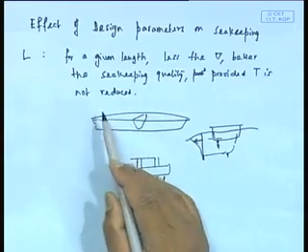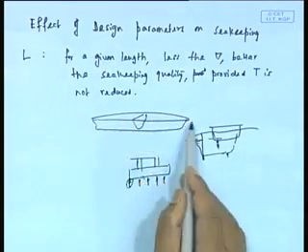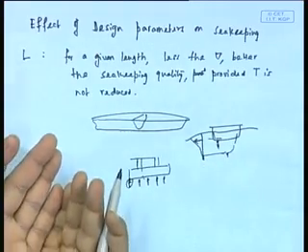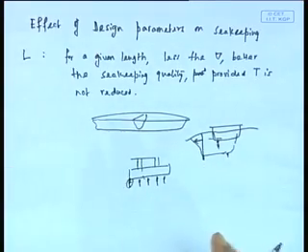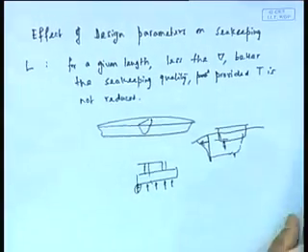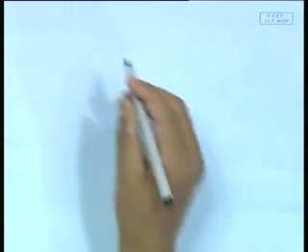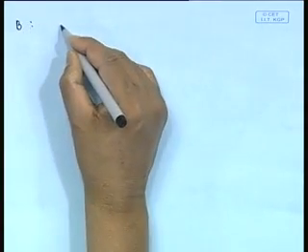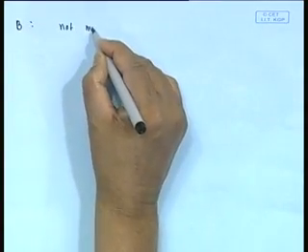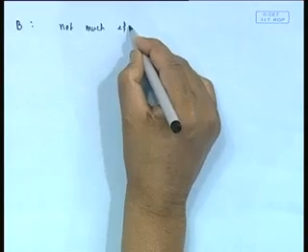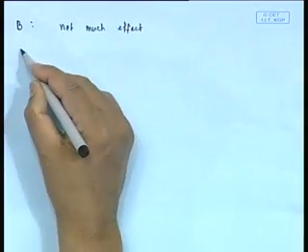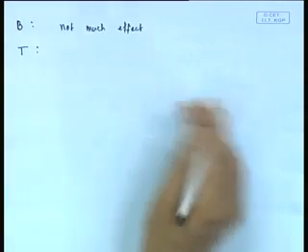Now, here in lengthwise seakeeping, it turns out that if you make it longer and finer, but don't make it too shallow in draft, you have overall better seakeeping criteria. Okay. Now, like that we can keep going. Beam, not much effect. There is some effect, but we are not going to go into this. Draft.